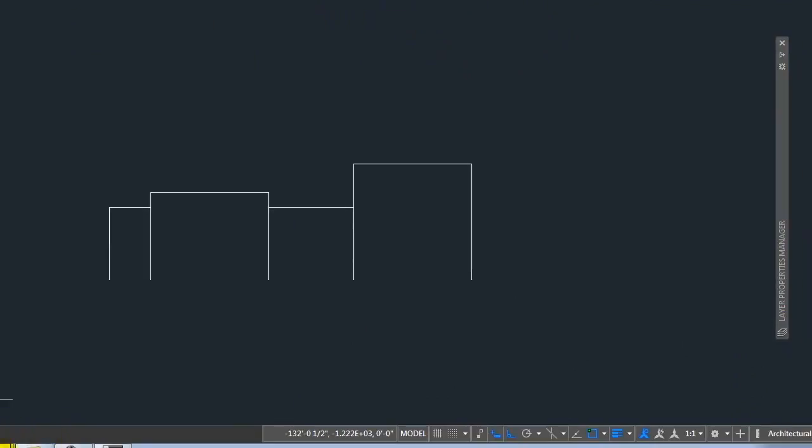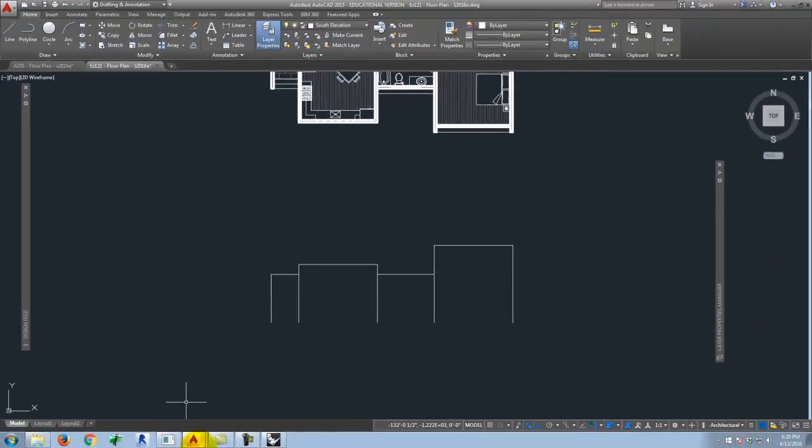I chose a flat roof because it tends to be the easiest to model, obviously. If you want to do something with a pitched roof, that's not a problem. What I would encourage you to do is to draw basically a floor and a ceiling at about 8 feet. Do all 4 of the elevations, and then I can help you construct the hip or valley roof depending on what you're trying to do once you have the elevations drawn. It's easier to do it in that order rather than try to do it all at once.